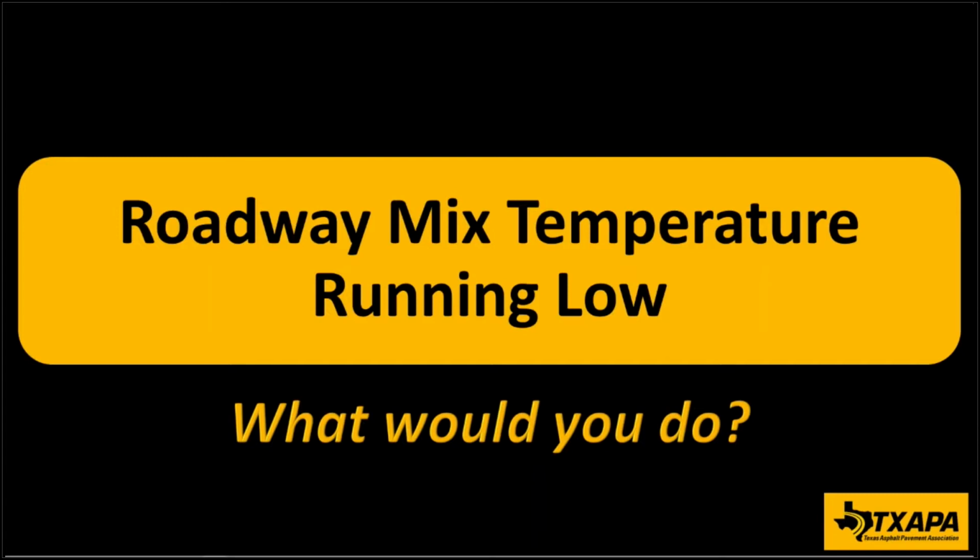Well, my first response would be, I need to check the mixed temperature at the plant. Start from the beginning and work your way back out to the field to try to narrow that down. Okay. Good. David, Madden, what would you do?